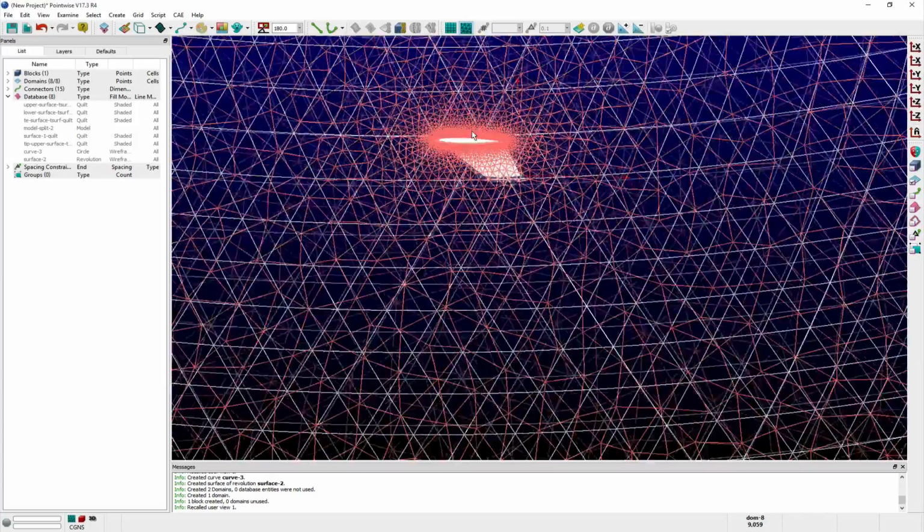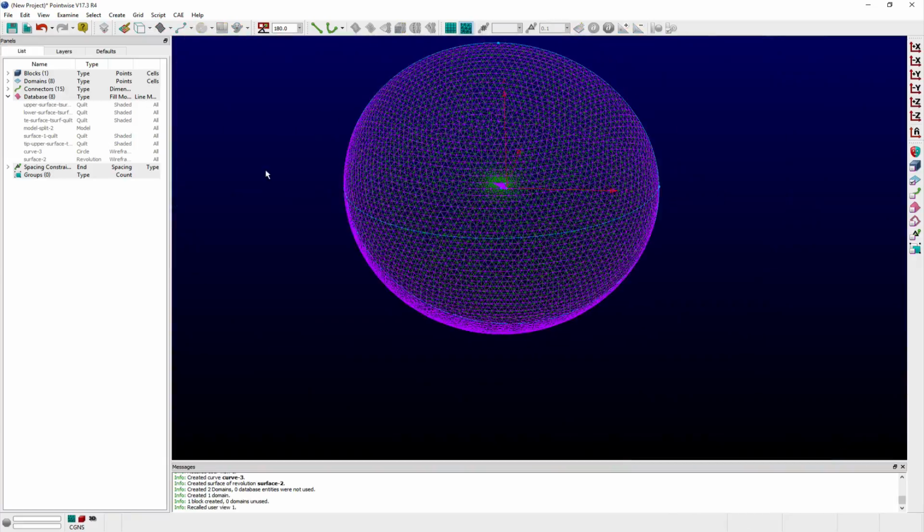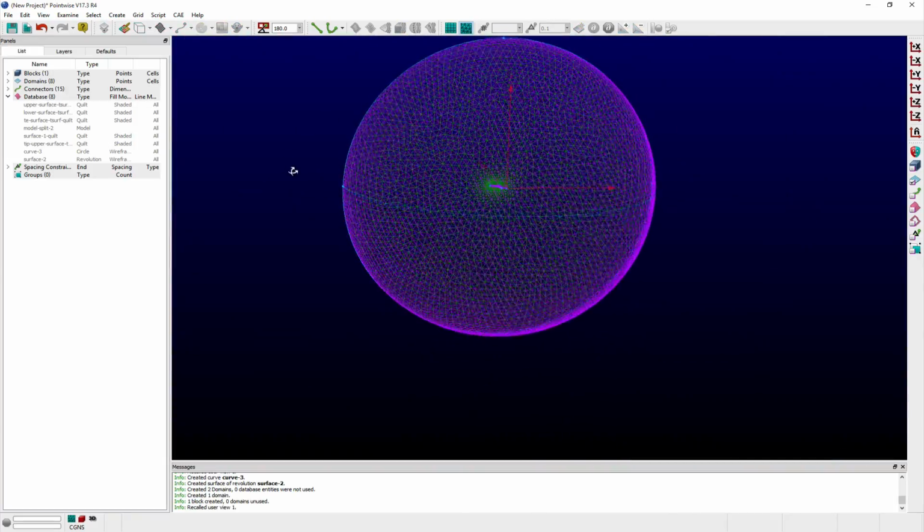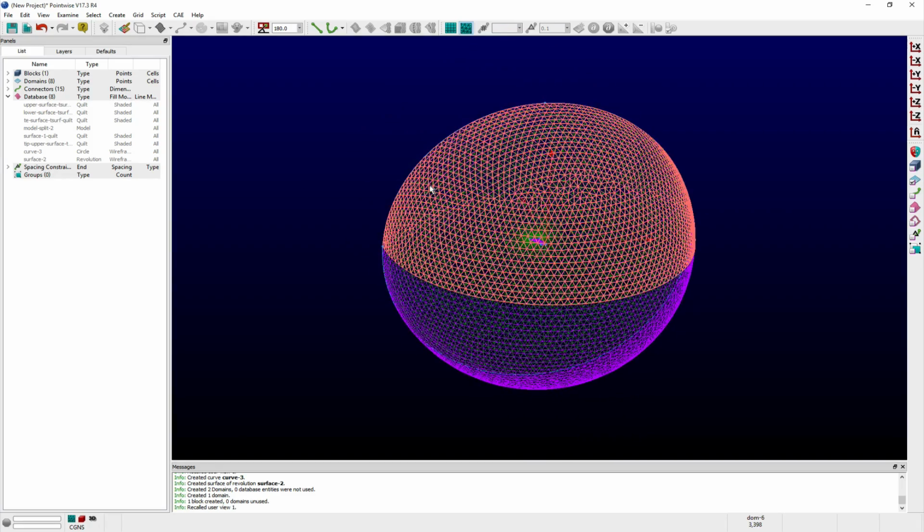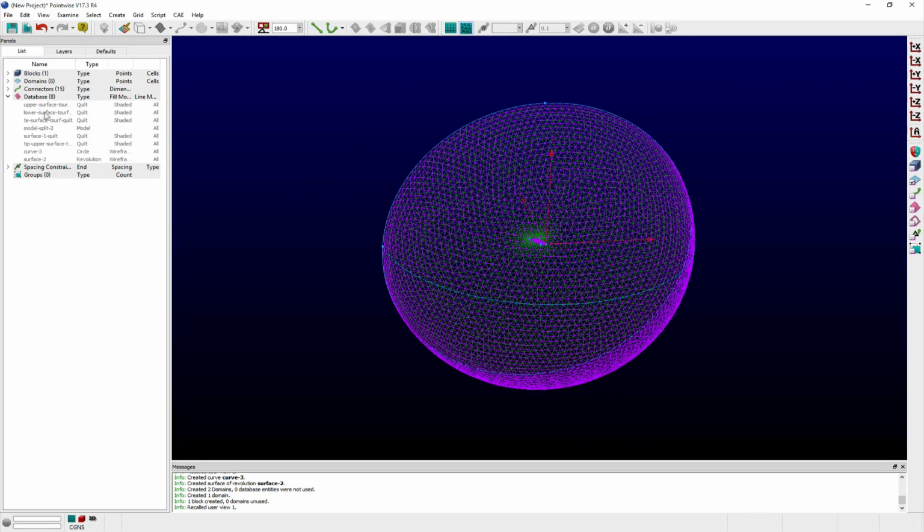3D T-Rex will be used to extrude layers of anisotropic tetrahedra from the wing surface and then fill the remaining interior volume with isotets. T-Rex will stop advancing layers from the wing surface once cells have reached isotropy, or a user-specified mesh quality parameter would be violated with creation of new tetrahedra. This allows a smooth transition of cell volumes from the anisotropic tetrahedral layers to the isotets in the interior volume mesh. It is also why having a uniform surface mesh where the area ratio of surface cells are below a threshold value of 4 is important.